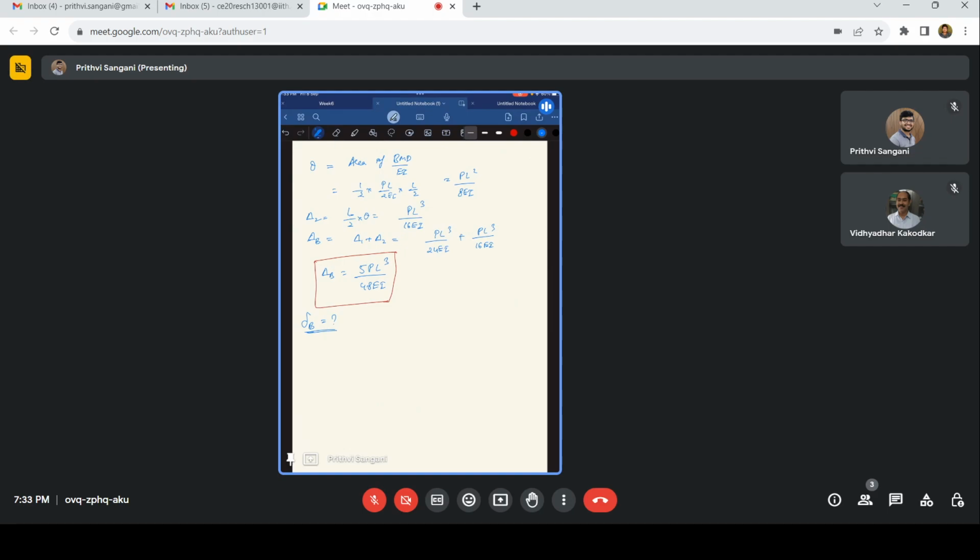For example, if a support is settling, it is kind of releasing its reactions, right? It is yielding down. So if it is yielding, that means the support is not going to take that much force, so it releases some reaction here. Initially without any support settlement it has to be 60, but right now it is 57.92. MB has to be 120, but it has actually become 107.5.